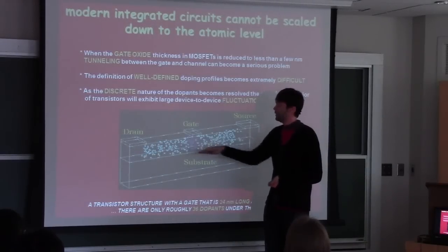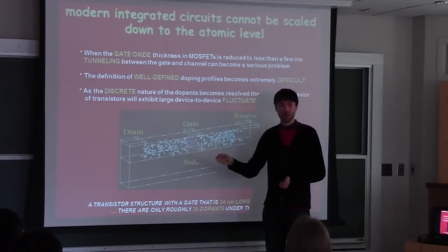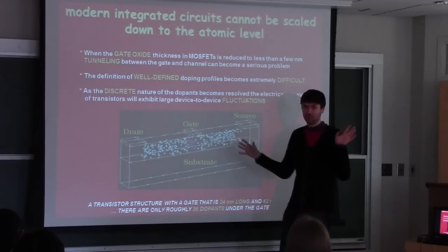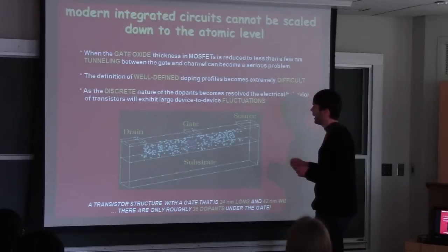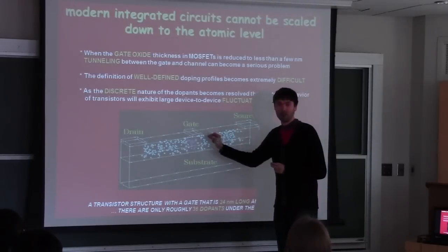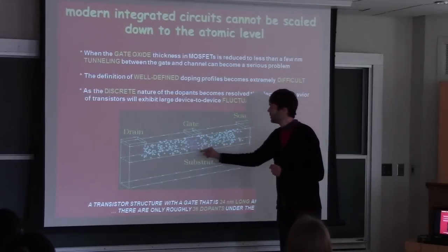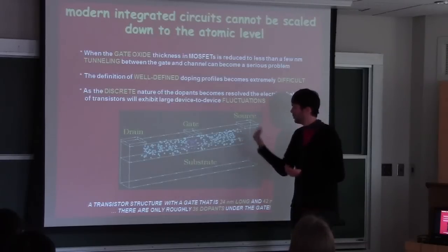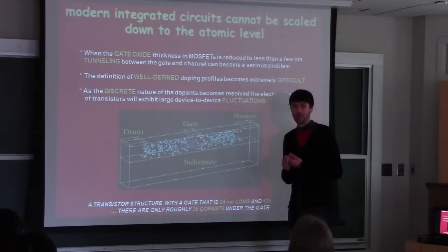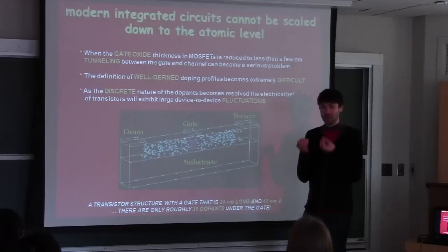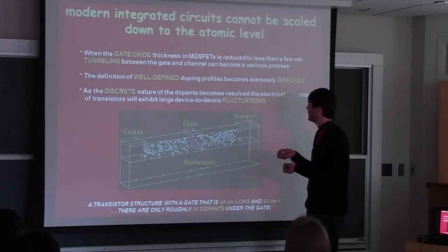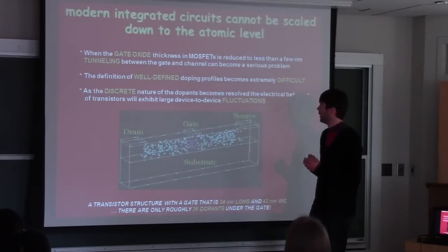It can change basically the occupation of electrons underneath the gate, and so it can completely block the transport or it can enable the transport. So the concept of gate is very important throughout this course. And the gate has become so small that the number of dopants that induce electrons in this channel is in the tens. In this simulation, it is 36 dopants. So we are really dealing with a discrete number of quantum particles, atoms, electrons, in the modern transistors.